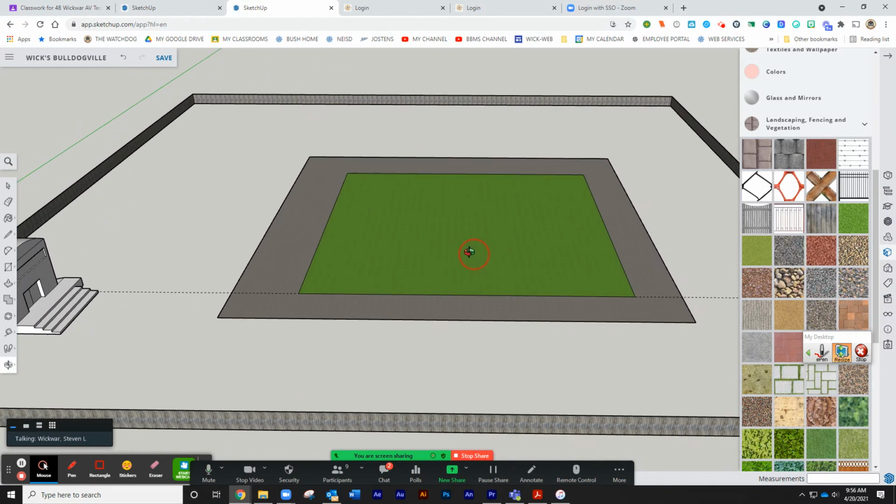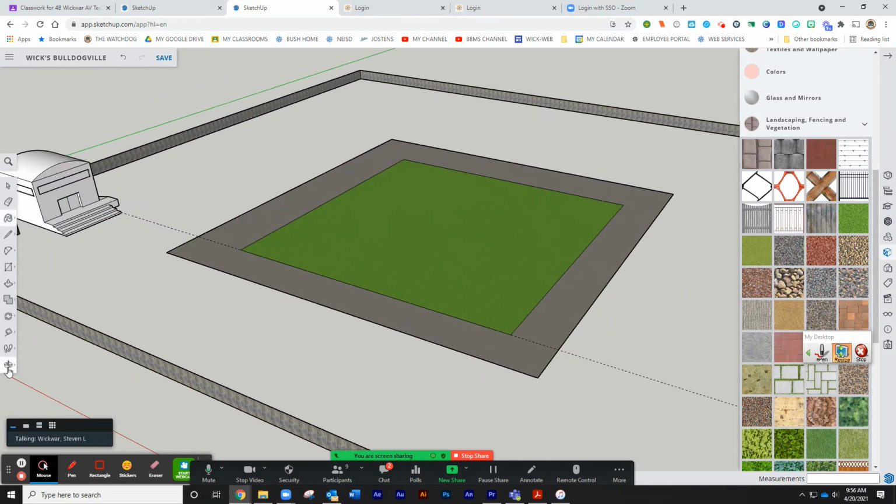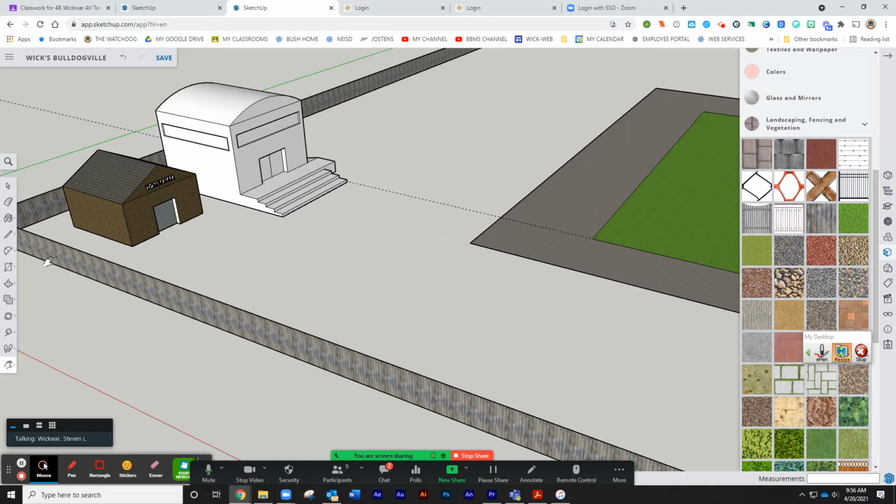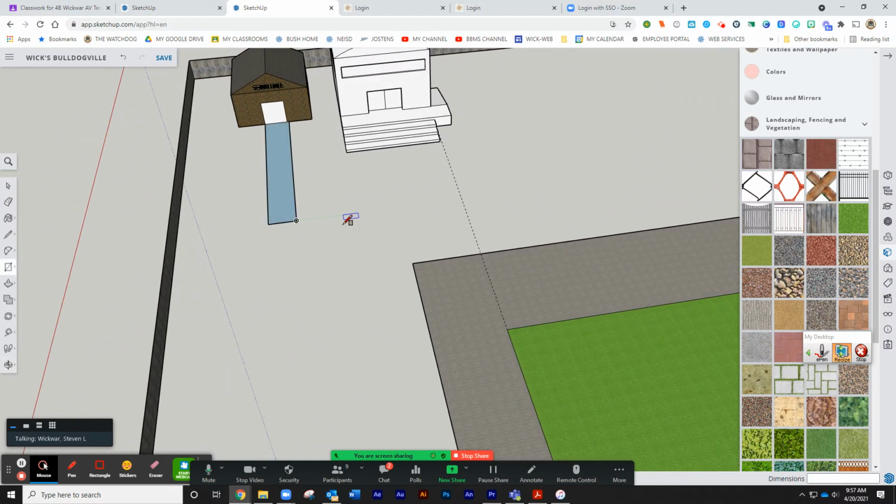Okay, pretty cool. If you wanted to do a walkway, which is another requirement, I'm going to scroll over here. You know, we would want probably some walkways that went down this way and moved around. Walkways are really just rectangles. So if you come down here and you find an area where you want to start your walkway, you really just have to know how wide it should be. I guess a walkway would be about 5 feet. And then I can just build off that. So here, same thing. I'm going to look in the bottom right-hand corner and make sure it's about 5 feet wide.